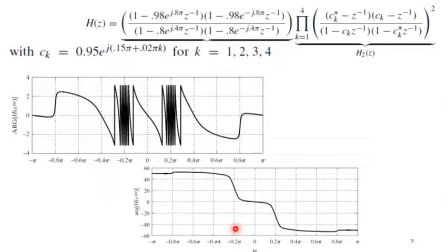Whereas in the figure below we have the continuous phase response. Here we have removed the jumps of size 2 pi. You understand, in the case of the principal value, we take just the tangent inverse, and there we have the range of minus pi to pi, or we can say the range is 2 pi.